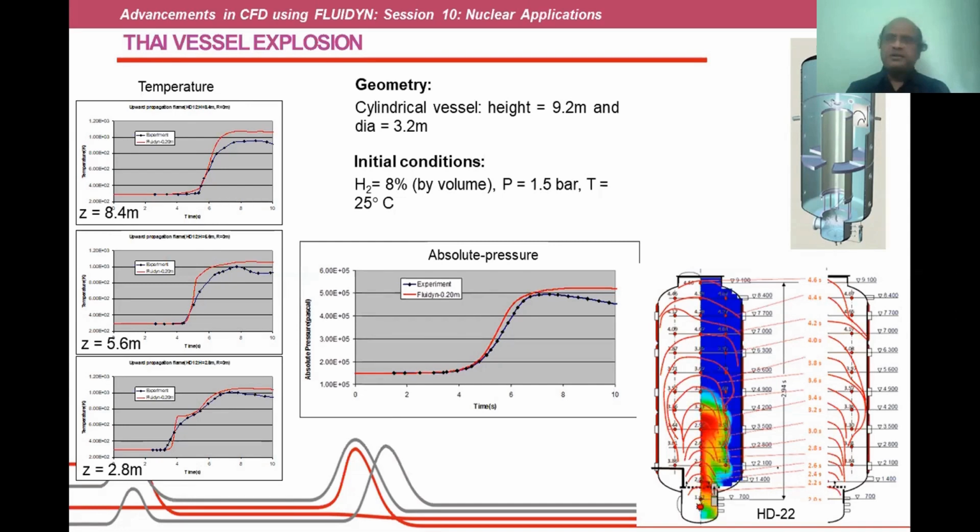And even if you use some sort of adaptive meshing techniques, there are still difficulties because we can see the flame here is actually widely spread. It is not restricted to a thin fan, especially in turbulence. The flame can be, things can take place in various places with this model. So certain special methods are required. The models were modified to get accurate results with the coarse mesh.